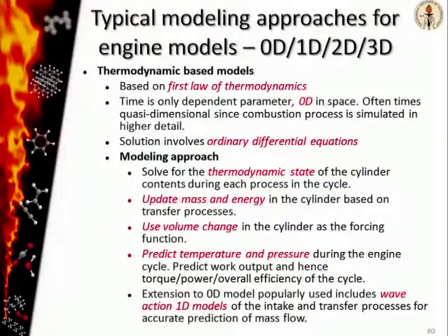So the typical simulation approaches that you see in engine models are thermodynamic and fluid-based models. Thermodynamic-based models are the simpler kind. They're based on the first law of thermodynamics. Time is the only dependent parameter. They're zero-dimensional in space, and the solution involves ordinary differential equations. So these are initial value problems where you have a certain boundary condition, and then you have a differential equation for each of the parameters that you're solving for, and it allows you to predict the thermodynamic state of the contents inside the cylinder during the course of the cycle.